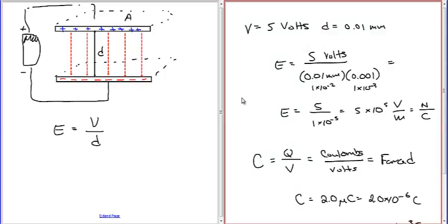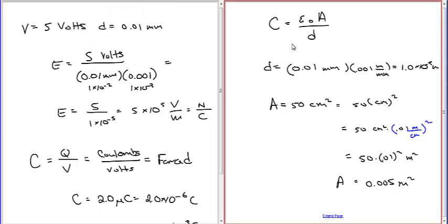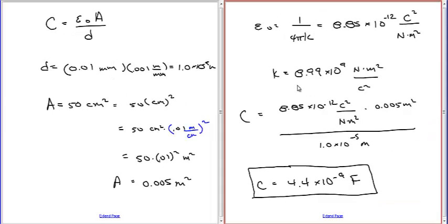Calculate the, given the voltage, there's the definition of capacitance. So if I gave you the capacitance and the voltage, you should be able to calculate the charge. If I give you 2 out of 3, make sure you can calculate the third one. Just simple rearrangement of that equation. The capacitance of two parallel plates based on the area and the distance between the plates, and this constant is using that. Make sure you write down epsilon 0 and K, so you have it to use. So this is calculating the capacitance given these three things. So simple calculation.